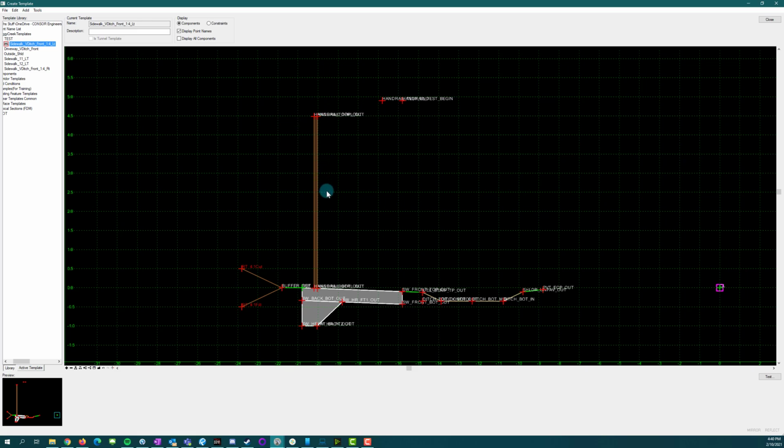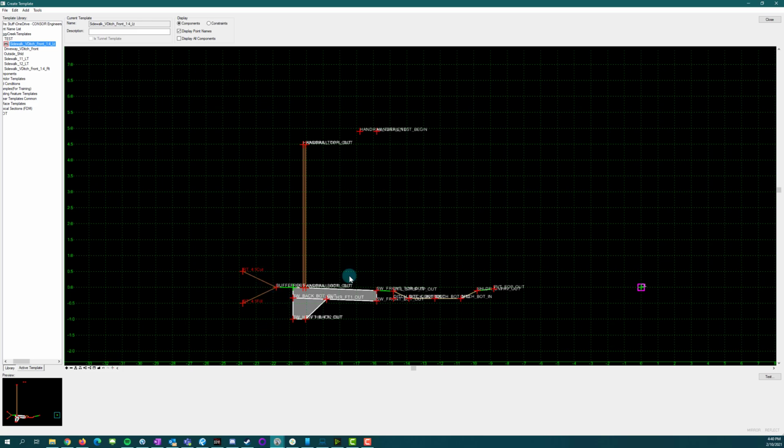We're trying to stay away from doing handrail on jobs like this because as you come up to a side street, if you need handrail, then the vehicle has a hard time seeing around the handrail at any traffic coming down the street. You don't really want to put handrail near somebody's driveway for the same reason. So in the job that I'm looking at here, I don't see any reason why we would have handrail unless we came up on some sort of end wall, or something like a pipe coming underneath the sidewalk here, and we needed to have an end wall here to get off-site water, or we had a ditch going this way or something like that.